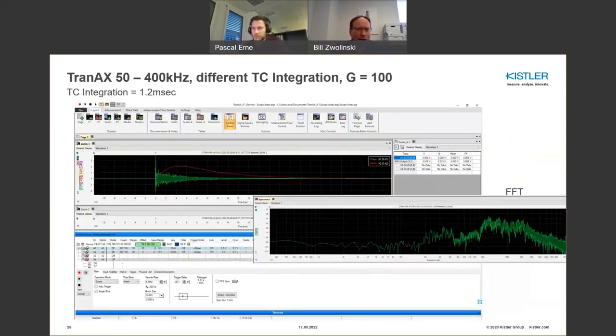This is just a quick idea of what it might look like with this Elsys system, a pretty intuitive system. You have a raw AE signal in the green, and you have the RMS output in the red, which I showed you. And this is an FFT of that signal. It's a logarithmic scale, but you can see somewhere around 50 kilohertz to 1 megahertz, you're seeing quite a bit of signal energy.